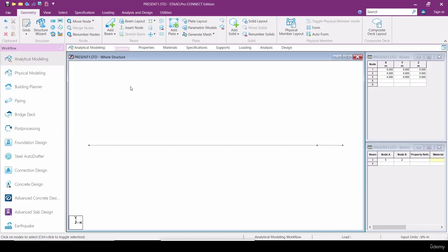And the next one is Shift B, beam numbers. Shift N is for node numbers, Shift B is for beam numbers. If you want to see the beam numbers, you can click Shift plus B. If you want to hide them again, click Shift plus B and they will be hidden. And F2 is the command to move: move any particular beam, node, or plate. Generally, we will not use plates here, but any component you can move with the shortcut key F2, the function key.